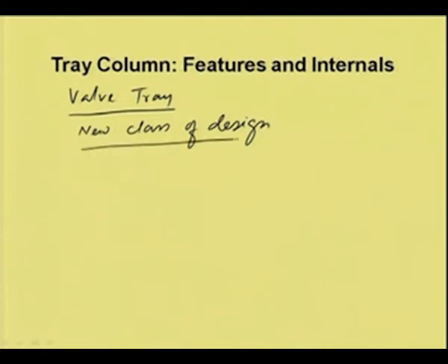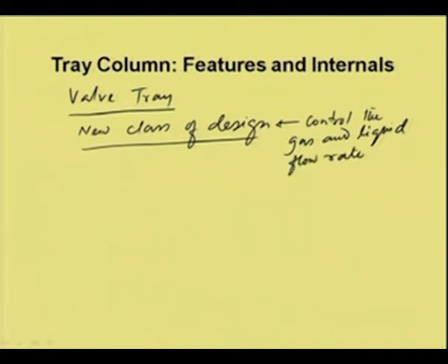Another type of tray is the valve tray. The valve tray is basically a new class of design, and it can control the gas and liquid flow rate by appropriate opening of the valve.